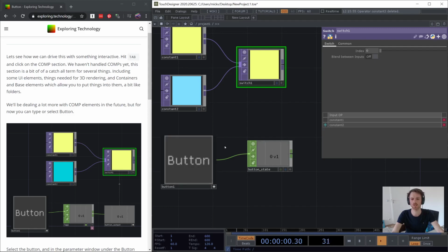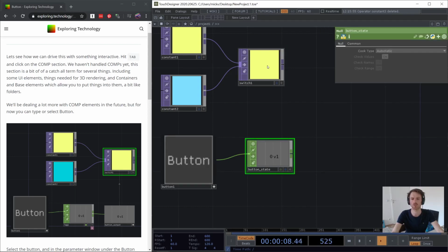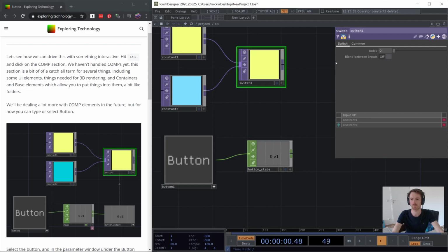This doesn't happen in the same way as the operators are happening over here and here with these wires. We're going to be doing this using a link, a reference. And the cool thing about TouchDesigner is that in all of these parameters, these values here are not just simple input boxes for text, but they actually are much smarter than that. If you click them and open them, they accept 4 different kinds of methods on how you can control the content of those parameters.